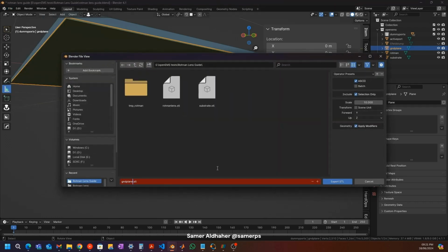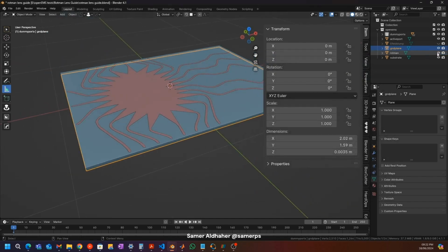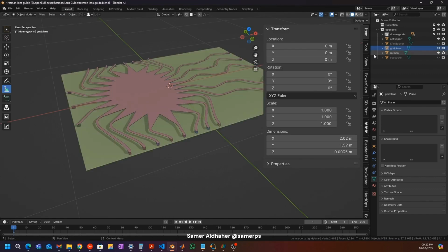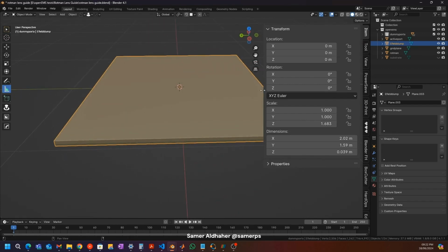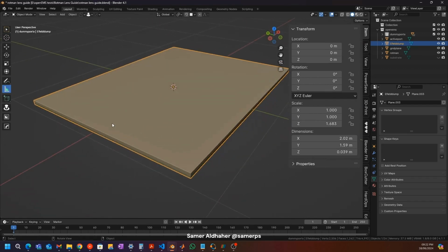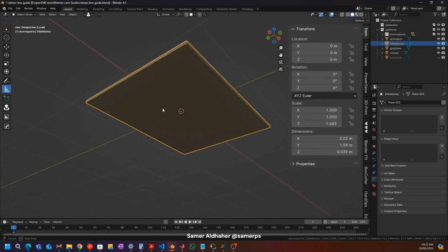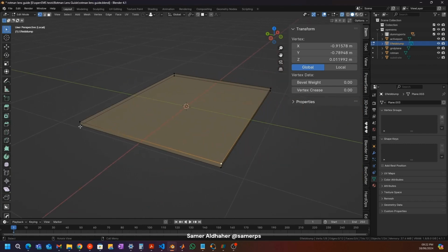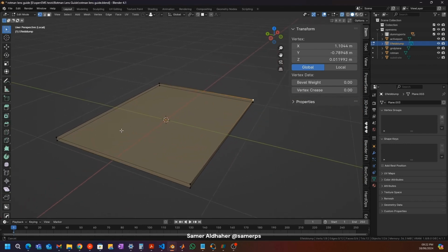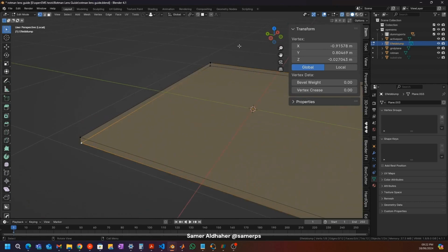Ground plane. Okay, and now let me just hide the ground plane, and let's first of all hide the substrate, not the ground plane. Let's bring in our E-field dump box. As I mentioned, we can't export this as STL, so we need to get the coordinates. If I go to local view mode, so I'm only viewing the dump box, and if I go to edit mode, I basically need to get the coordinates of the vertices of this cube. So I'm going to select this one, and I want this one, so it needs to be 2 extreme corners. In Blender, if you go to Item here, Blender will give you the coordinates.